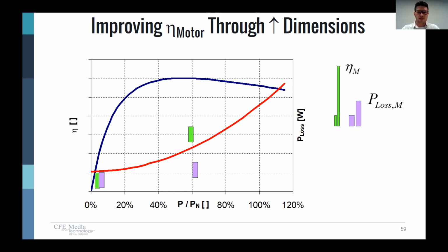Well, if you look at that curve, you can see the efficiency. If you back off from 100 to about 60 or 70%, the efficiency actually goes up a little bit. So we have a motor that's capable of, let's say, 5 horsepower, but we rate it for 3 horsepower to try and get into the sweet spot where the efficiency is a little bit higher. Now we have a more efficient motor. That means we're not going to have as much heat loss because that motor's not working as hard. And those heat losses are the main source of losses that we're trying to avoid.